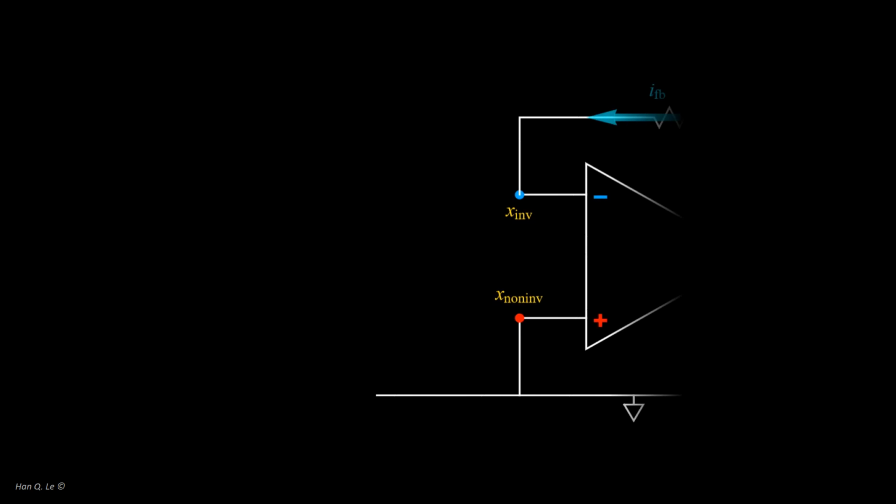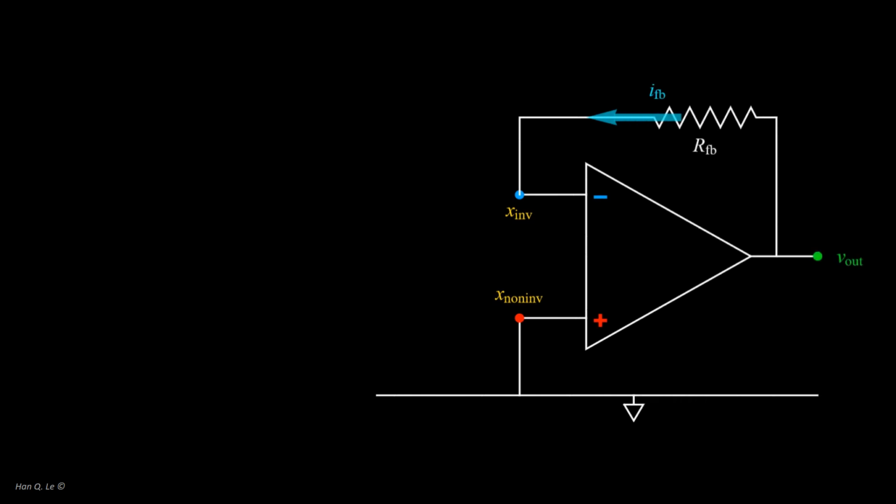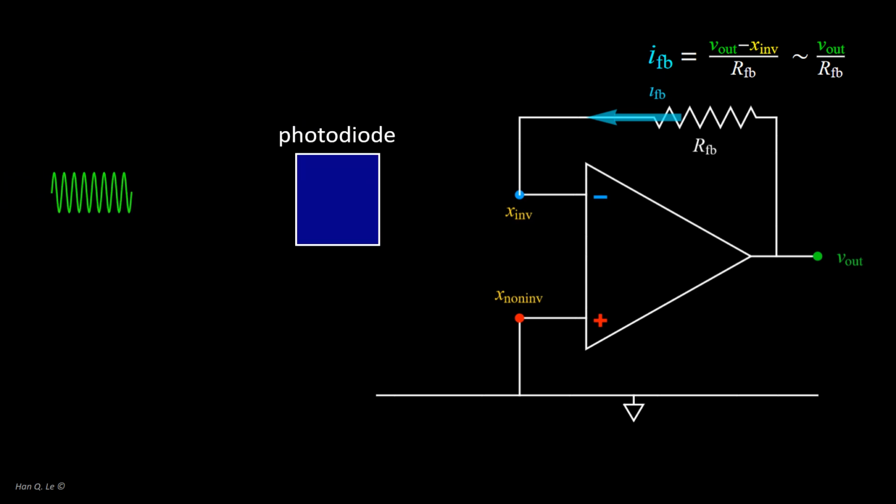At the most basic level, a learning objective is to study the op-amp as a current-dependent source, as opposed to the voltage-dependent source in Part A. The negative feedback here is to control the voltage output from the input current. The photodiode acts like a current source, where the current magnitude is proportional to the incident light power.